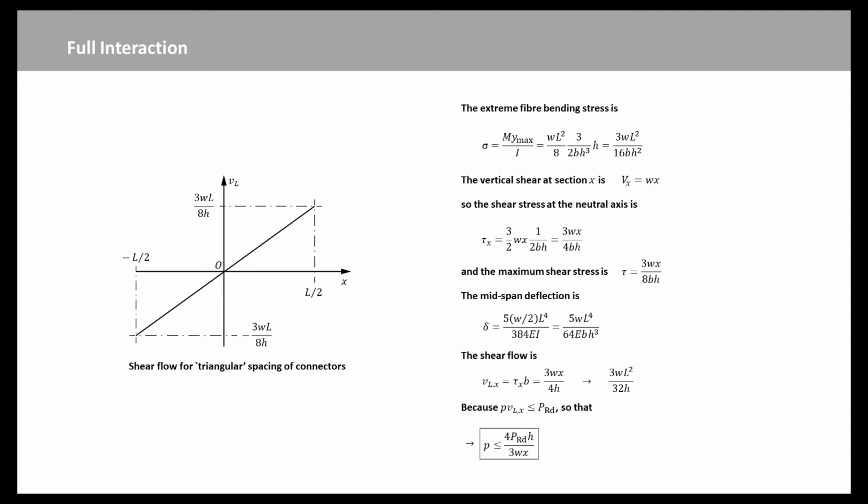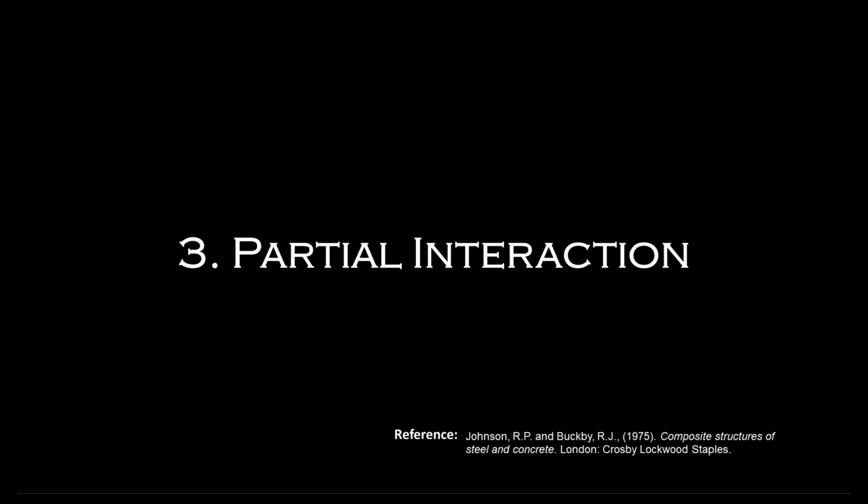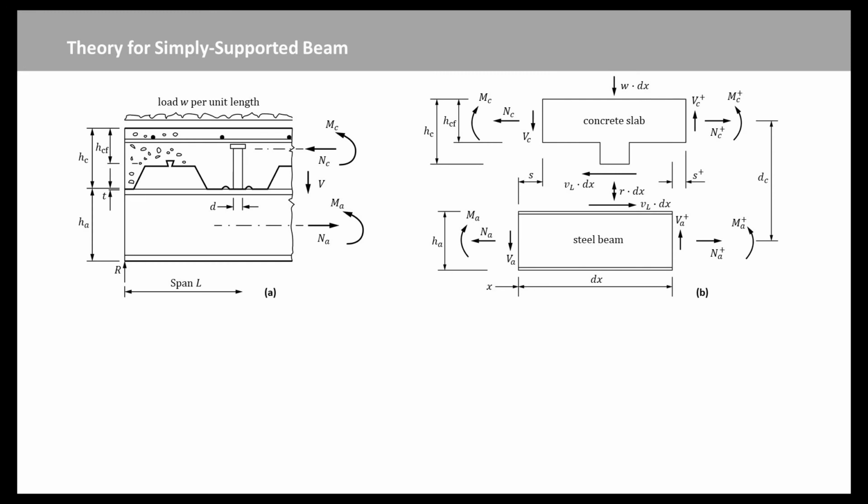However, the results of push tests show that even at the smallest loads, slip is not 0. Therefore, it is necessary to know how the behavior of a beam is modified by the presence of slip. This is best illustrated by an analysis based on elastic theory. It leads to a differential equation that has to be solved afresh for each type of loading, and is therefore too complex for use in design offices.